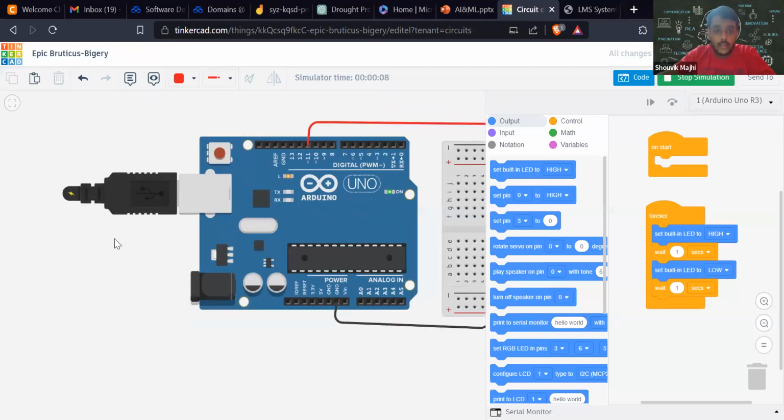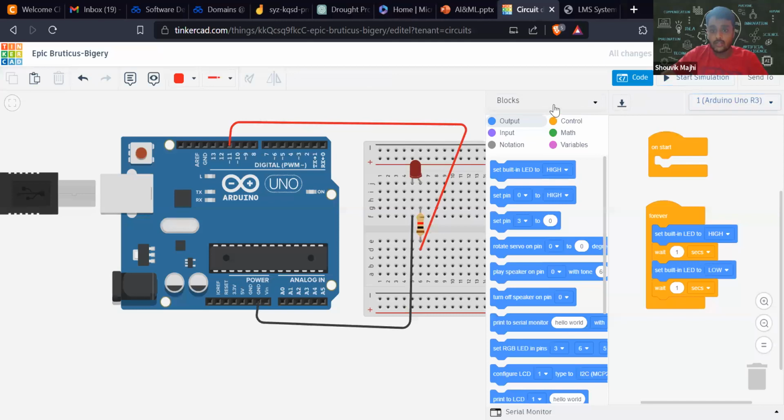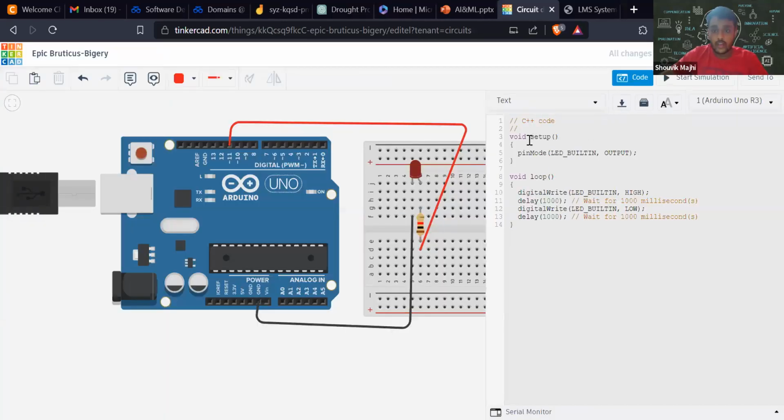Now our main task is how to control this LED with this Arduino. So let us go to code over here. There's a void setup section. This setup section tells you how to set things up for the Arduino. You have to set a pin number. We are using 11 over here, and the type of device. In terms of LED, it is definitely an output device.